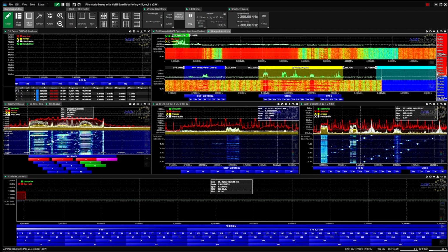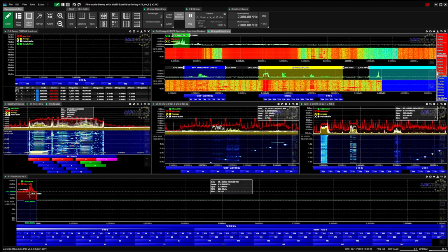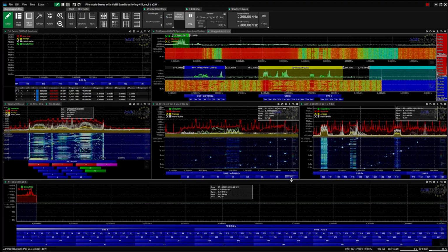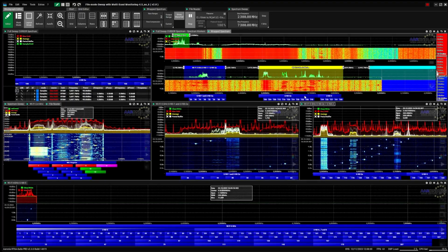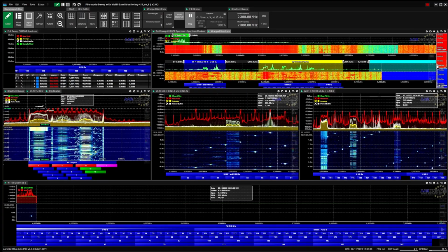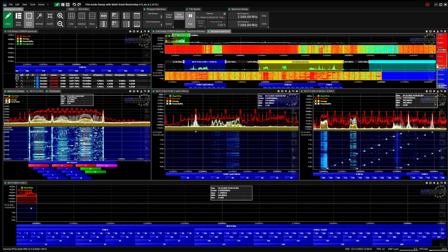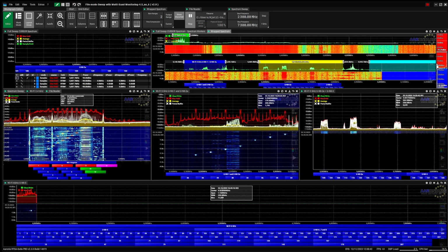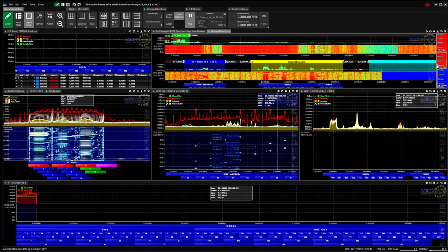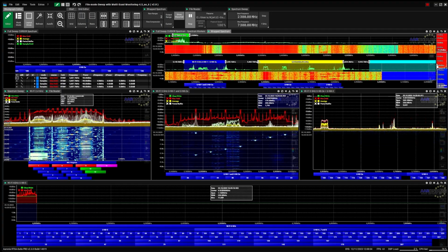Let's see, this is something on 6 gigahertz. If I move this all the way down to channel 1, there, you see that I did have something at 6 gigahertz right here. So for all us people waiting for multi-link operations in Wi-Fi 7, here you have the possibilities to look at 2.4, 5, and 6 gigahertz at the same time. And you can even look at any interfering devices that is hiding between Uni 2A and Uni 2 extended that could interfere with our Wi-Fi.